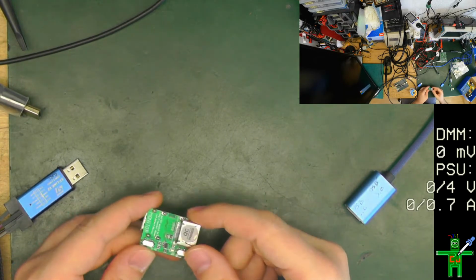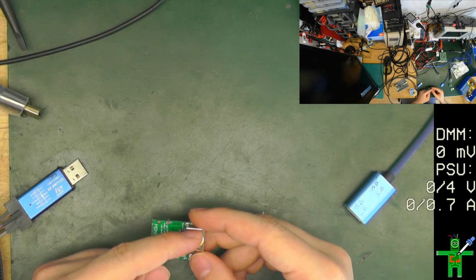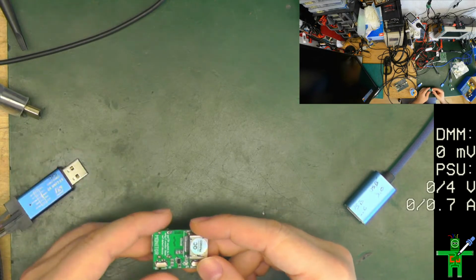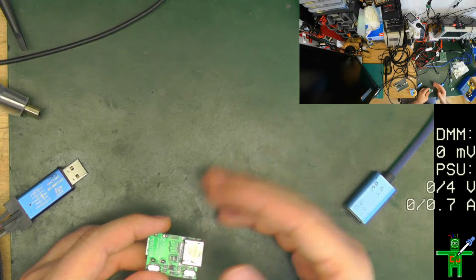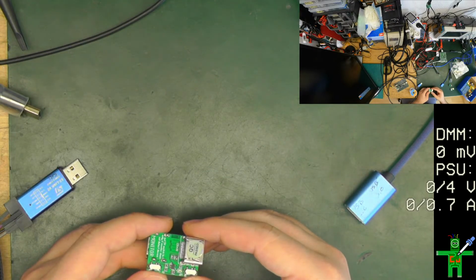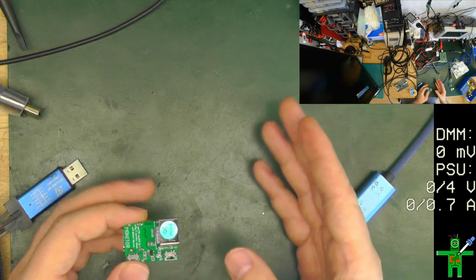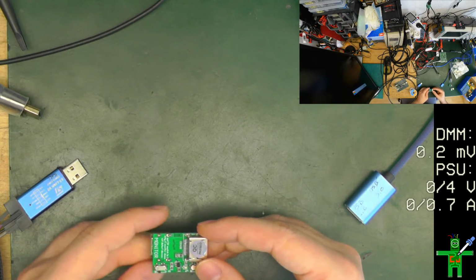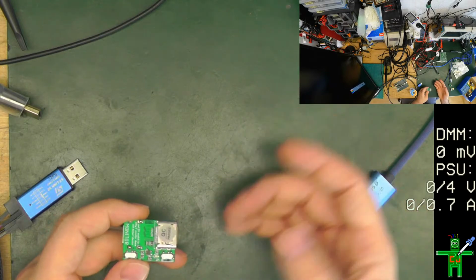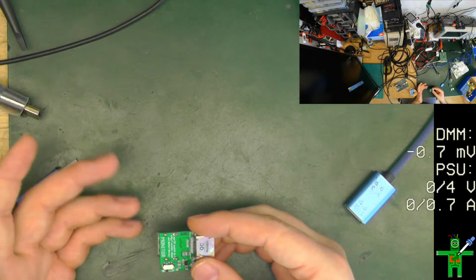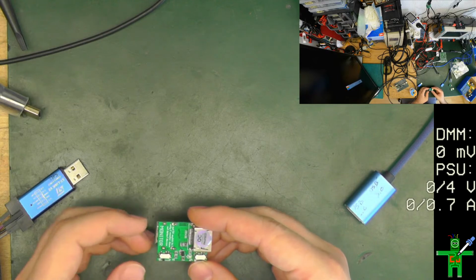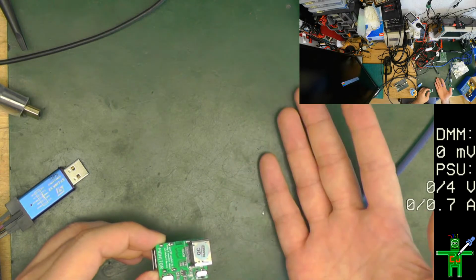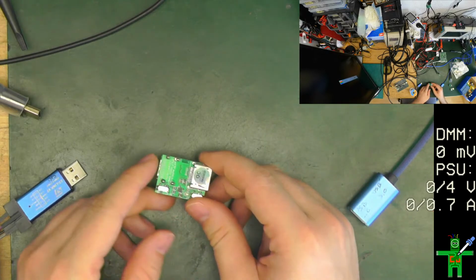When you connect over HDMI, you have to read out the monitor. I'll say the monitor for now, but very often they are called sink in the specification, but I'll just say monitor. So whenever you connect your device, which is normally called the source, to the monitor, which is normally called the sink, then you read the information about the monitor, what resolution it supports, what refresh rates, and so on. This is the EDID information.